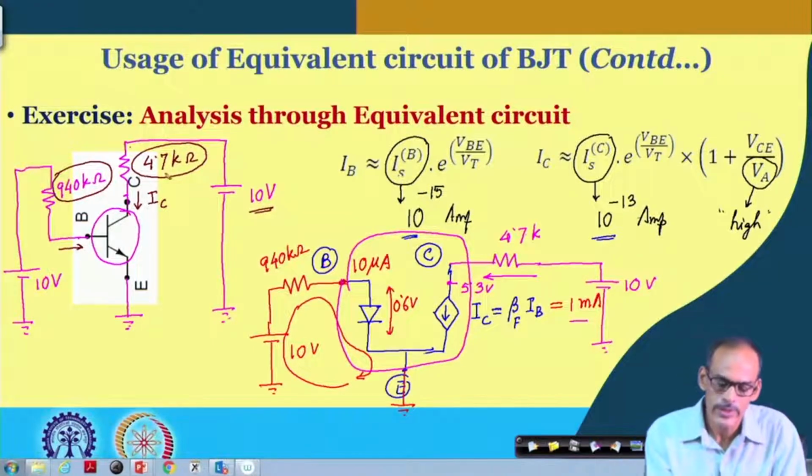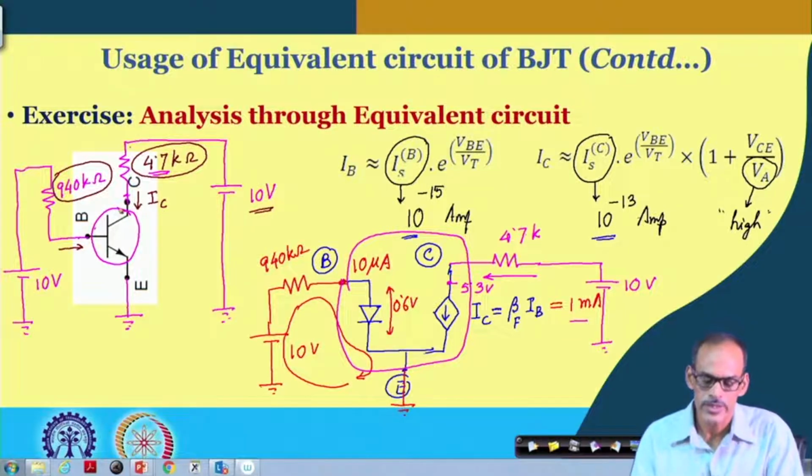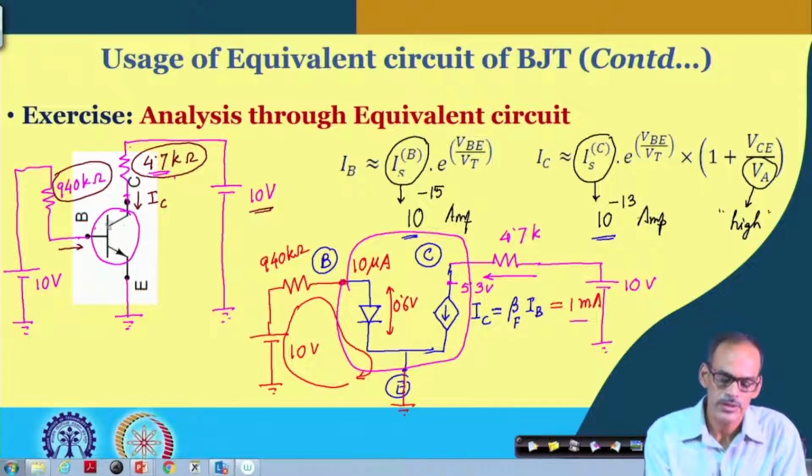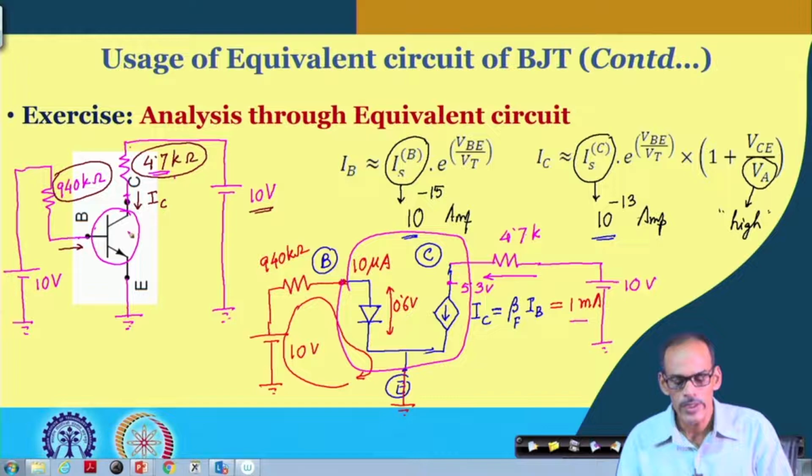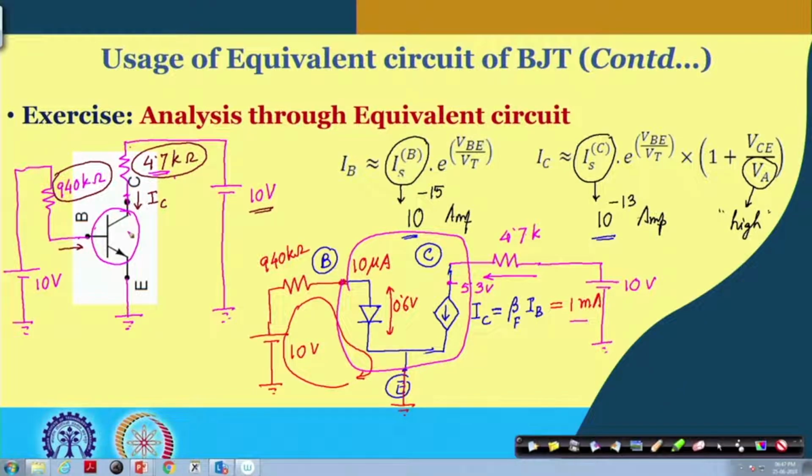In fact, if you increase this resistor, this voltage will drop, and beyond some point this junction will get forward biased. If you further increase this resistance, this transistor will enter an altogether different region of operation called the saturation region. So, we will go into a little more detail with this kind of circuit. In fact, we will be varying this voltage, and then we will see what kind of variation or effect comes to the collector side, that detail when we will be dealing with the amplifier.